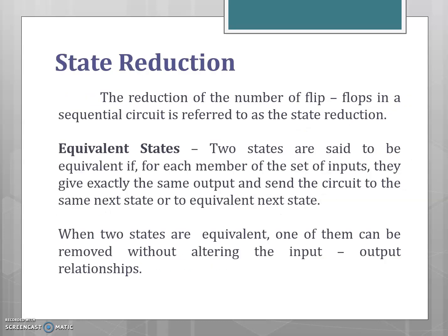So next, coming to the state reduction. This state reduction algorithm reduces the number of flip-flops required to implement the sequential circuit. So this state reduction reduces the number of states and thereby reduces the number of flip-flops.